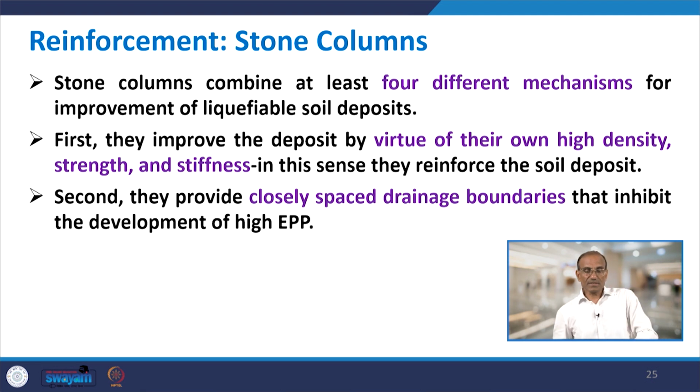So, stone columns combine at least 4 different mechanisms for improvement of liquefiable soil deposits. What are those mechanisms which the stone column helps? First, they improve the deposit by virtue of their own high density, strength and stiffness. In this sense, they reinforce the soil deposit.